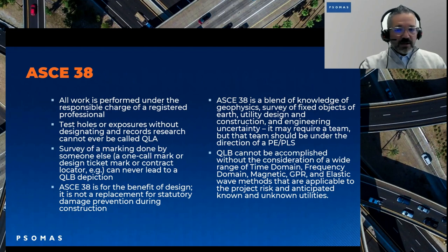Survey of a marking done by someone else, a one-call mark or design ticket can never lead to a QLB detection. If you or someone that you hire did not do that utility detection, you should be calling that a higher level of risk because you don't know exactly the methods they used. You don't know how they went about locating it.